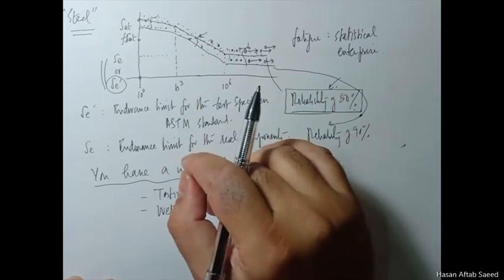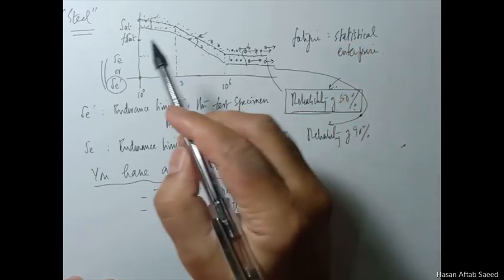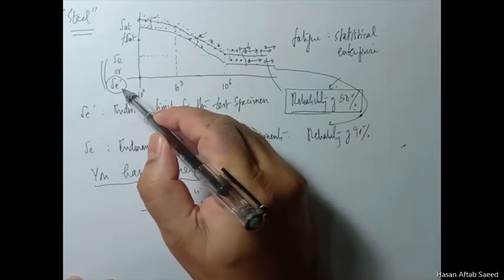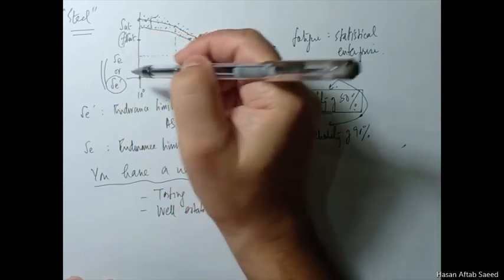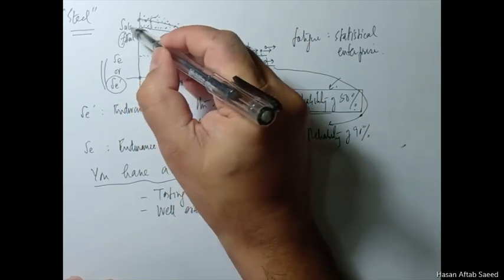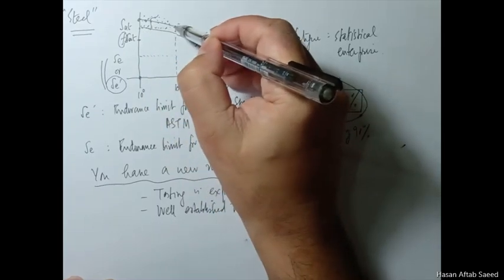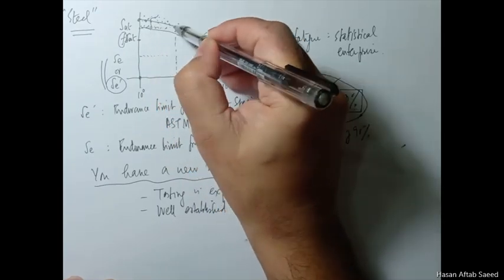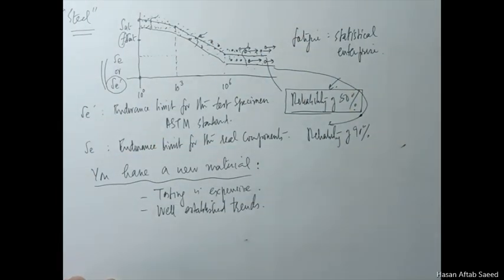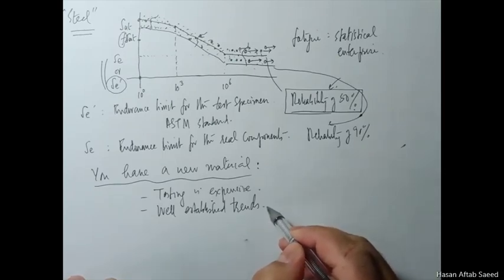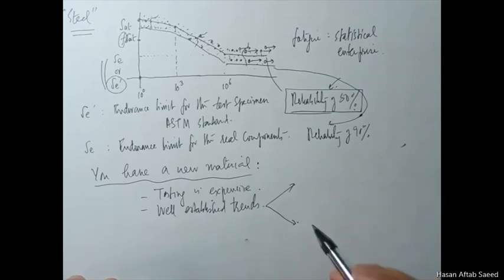We know that for a certain tensile strength, what the endurance limit is, or for example, what this fraction f is that you have to multiply the SUT with to get the residual strength at 10 raised to power 3, which is the end point of the low cycle fatigue. So two such trends are very important, and we'll be using them a lot.